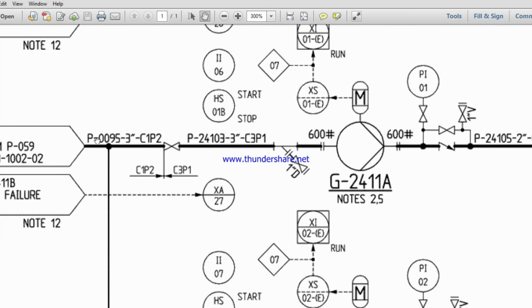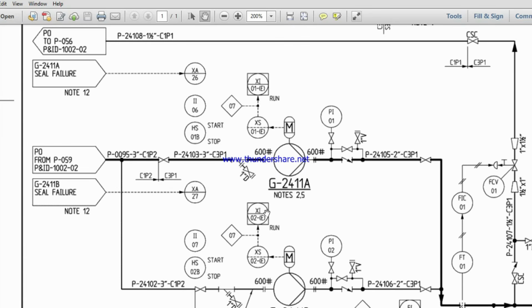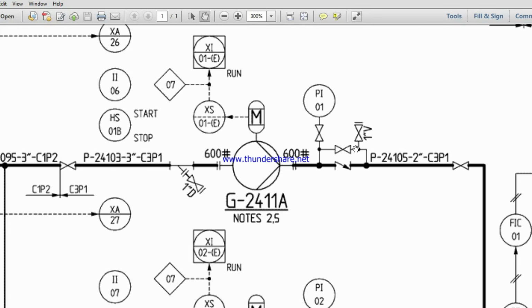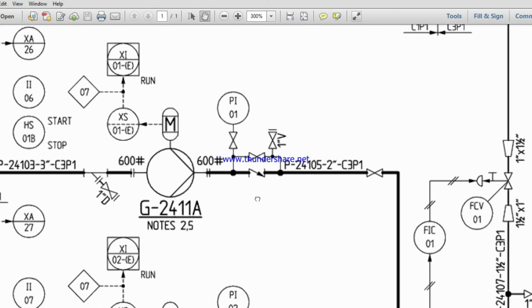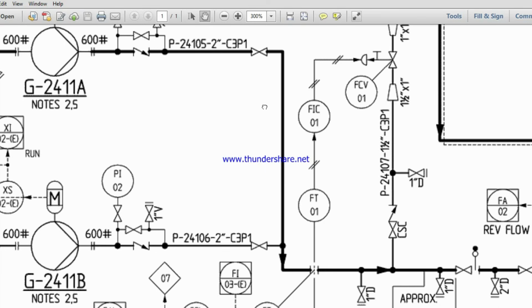Piping specifications are to be shown for each pipe, along with the junction points where two specifications join. We use breaks where we have two different materials, tracing or insulation in connect. It is shown like this. All the different types of valves which are going to be used in the plant are to be shown in the P&ID, like check and gate valve symbols used here.